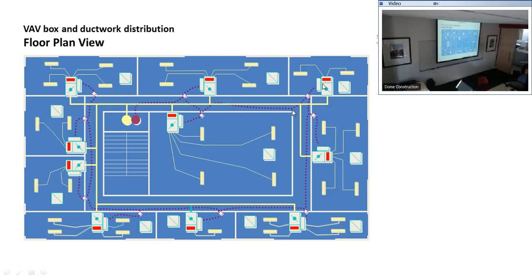You see what this box is and all these little diffusers. Now you know you're looking at a VAV box. And some type of symbol here that means this box has a reheat coil. Who picks up the water for that? The VAV? That's under the mechanical, HVAC non-plumbing. So that's part of the hydronic system that the mechanical guy picks up. Not the plumber.